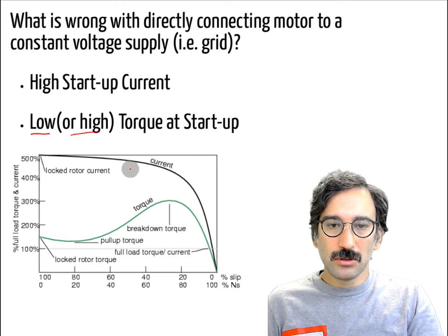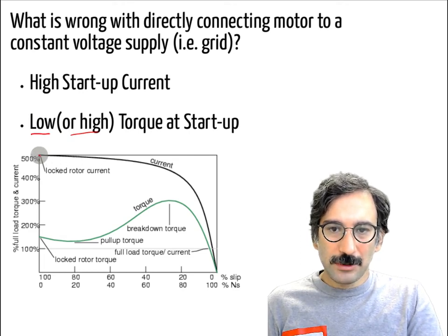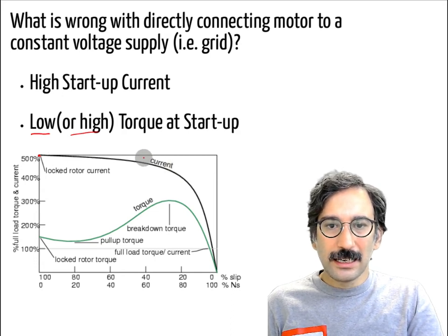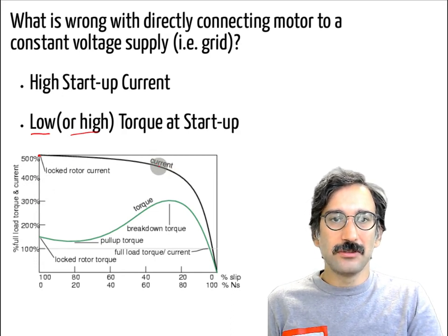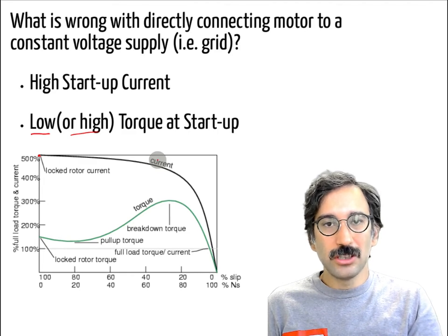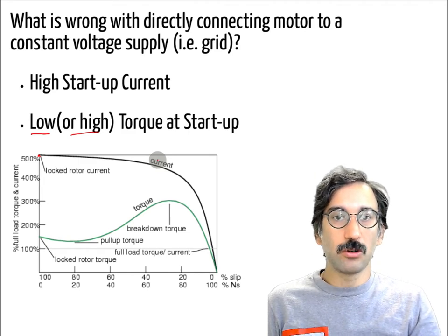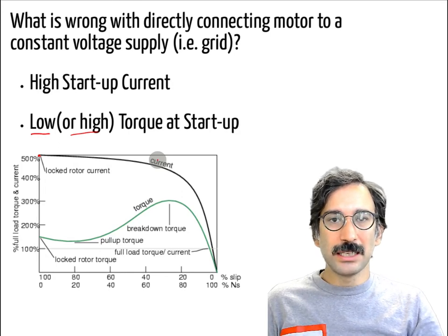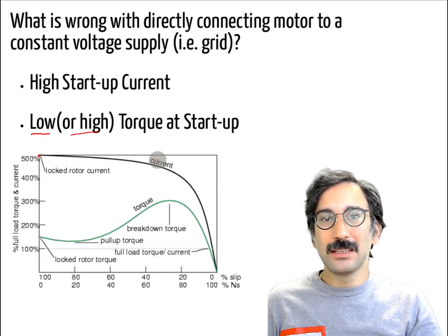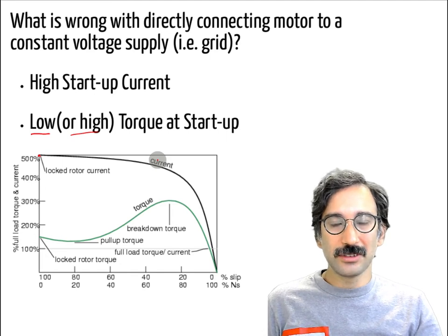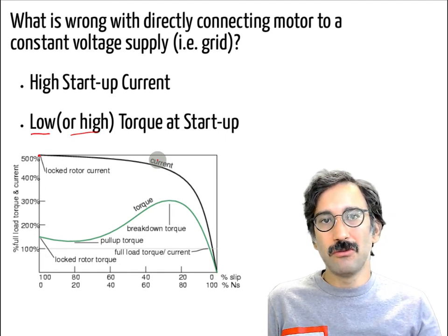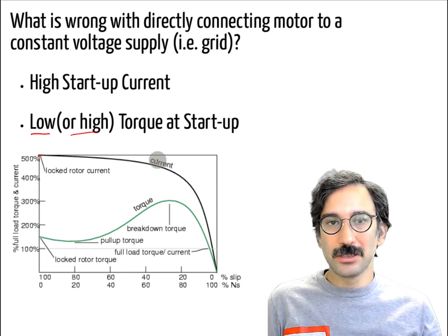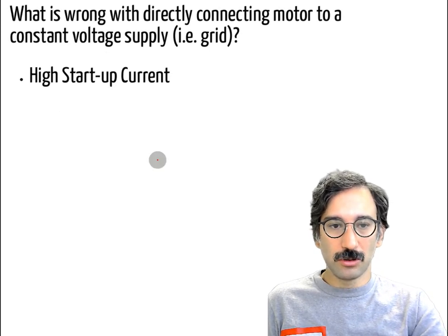Here you see the current is like 5 times the rated value, so the machine will generate 25 times more heat in the stator coils. But that doesn't always mean that drawing 5 times more current will convert to 5 times more torque, or 25 times the rated torque. Why?